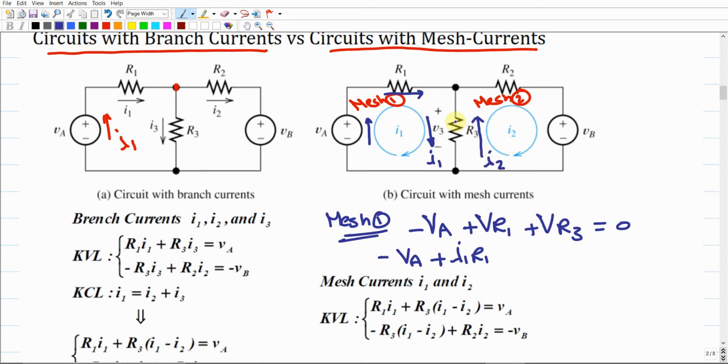It is not physically this case, but you can assume that we do have two different speeds, and these two electrons interact together over this branch, over this electrical element. So in total, the current over R3 should be the difference between I1 and I2. Why the difference? Because they are moving in opposite directions. So one will be positive, the second one should be negative.